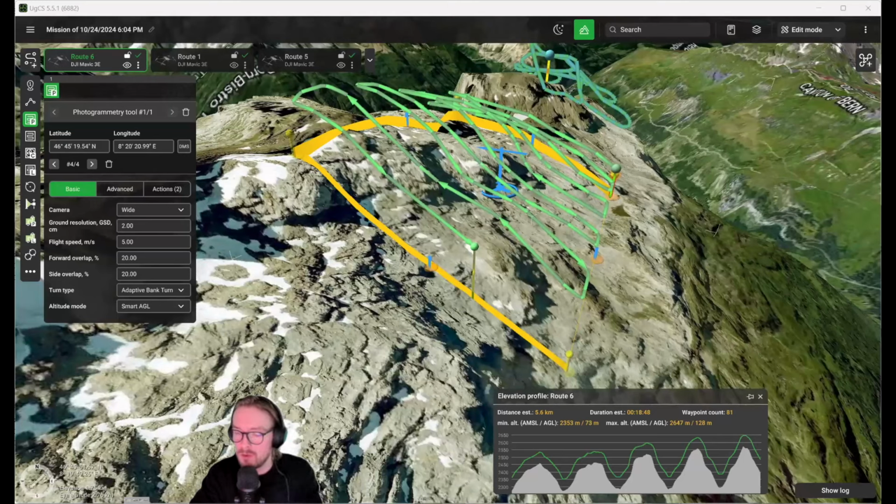And okay, let's move forward into the questions. Oh yeah, from Bennett: what drone and what sensors were used to collect this example data? Sure. In this case, the data we gathered over the polygon was gathered using a Mavic 3 Enterprise drone. So just your standard Mavic 3 Enterprise with its wide camera was what we used to collect this dataset. I believe if you used something like an M300 or M350 with the P1 camera or H20, you'd probably get even better results from this.